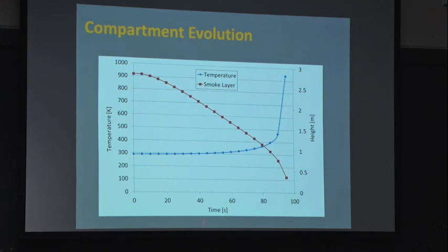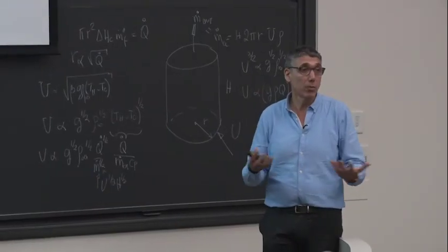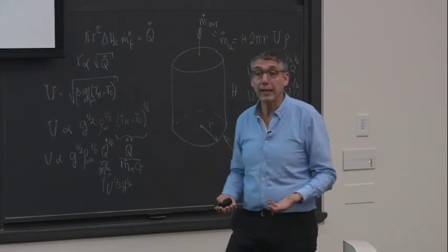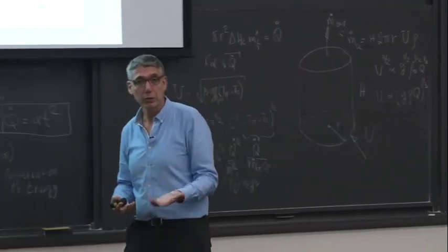If I'm confident that the solution ends up here at 80 seconds, I can call flashover here. My error bar will be 20 seconds, but who cares? I'm going conservative. So I'd rather have a simple solution with none of these corrections than start correcting and correcting and correcting, and then kind of lose track of how these corrections are affecting the solution. Is that okay? But that's a decision that obviously an engineer will have to make on the basis of what they're trying to achieve.